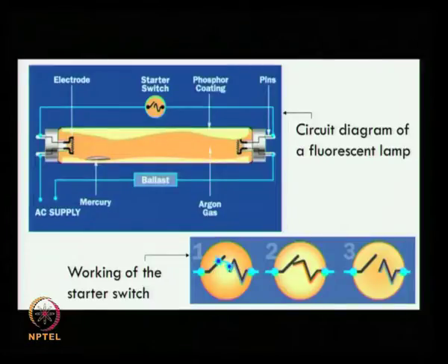This forces the ballast to generate an electric arc through the now fully ionized gas. The electrons from the arc excite vaporized mercury atoms, releasing ultraviolet photons. These photons excite phosphor atoms, emitting visible light.